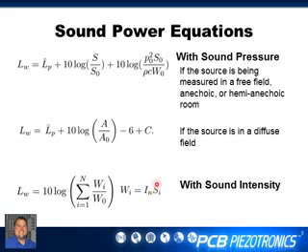And in the last equation here, you see sound intensity, which is actually directly derived from sound pressure, both between the sound pressure and the particle velocity, which is derived from sound pressure. So no matter what you're doing, whichever one of these equations you're looking at, it starts with a sound pressure measurement with a microphone.